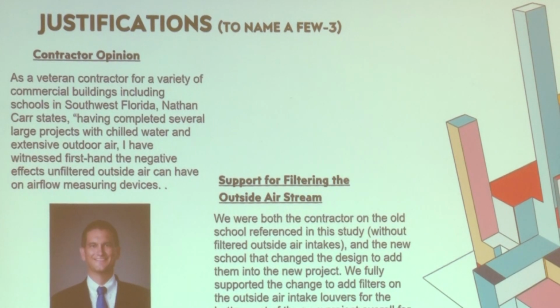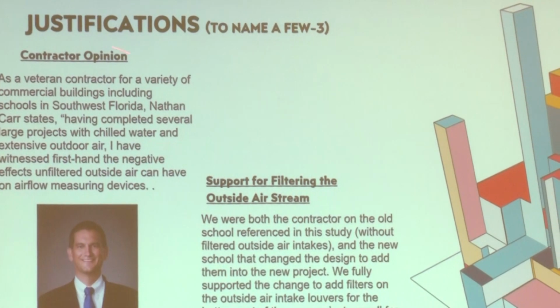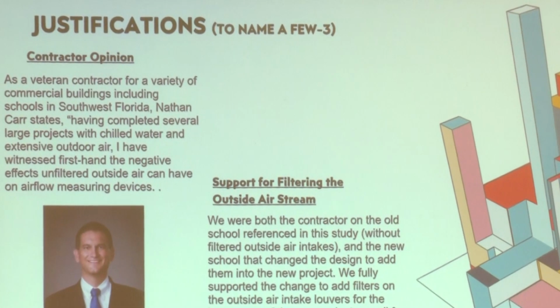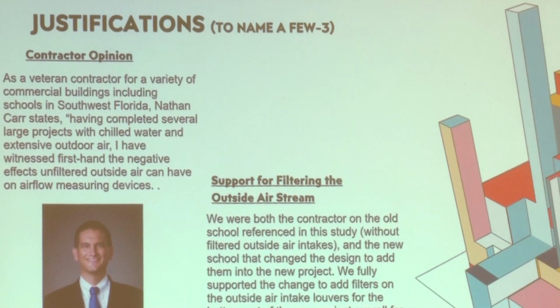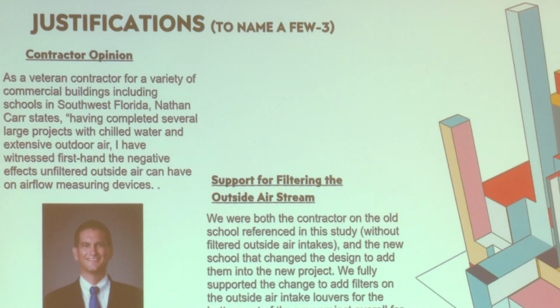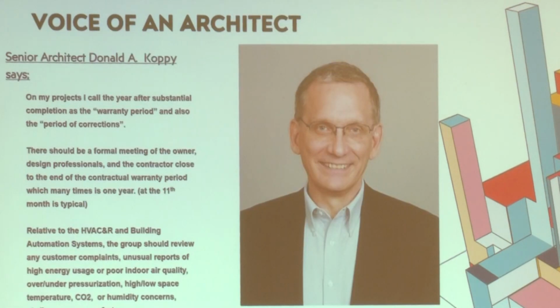So what I did is I went out and I got a contractor's opinion. This is a contractor that happens to do the schools that we actually did the case study on. He's a contractor and an engineer as well, and he agrees that in all of his career, he sees this happen all the time. He says, we install airflow monitors, we regulate the amount of air that comes in, we test it, we balance it, and then 6 months later, it doesn't work anymore. We have a lot of support for this. Both the contractor and the owner agree, and we use this as a test case.